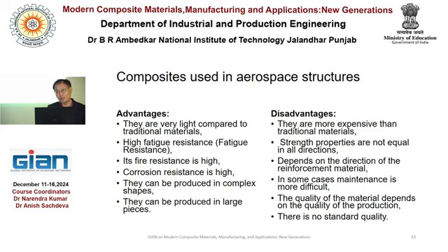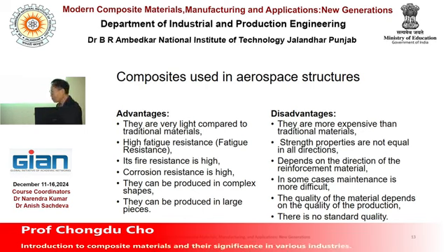So aluminum is much less durable. Aluminum deteriorates every time due to fatigue. Aluminum cannot sustain even at a very low stress range, because the S-N curve has no limit, as you see. So it's a slow decline.